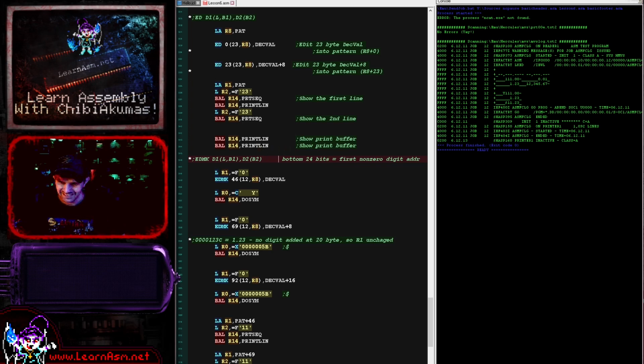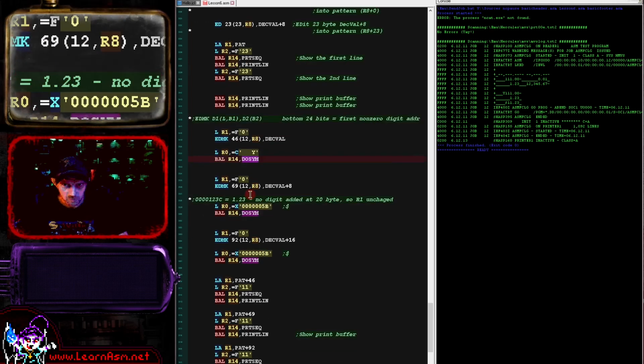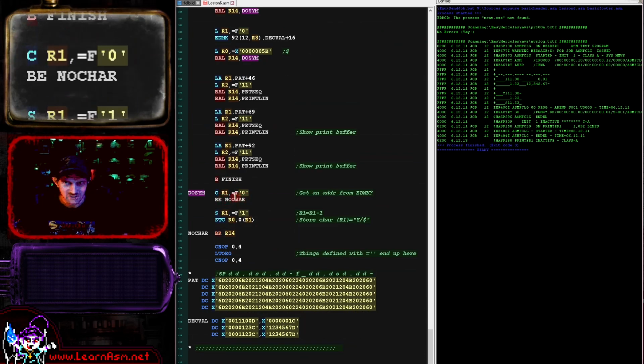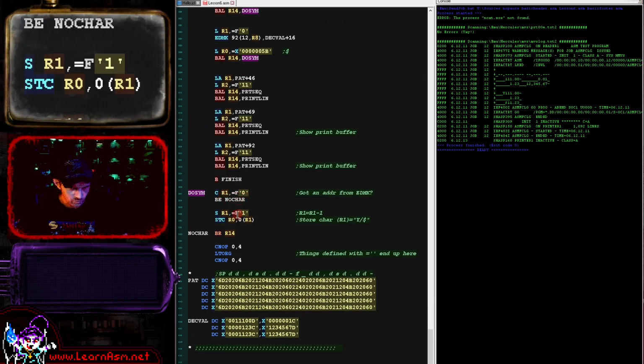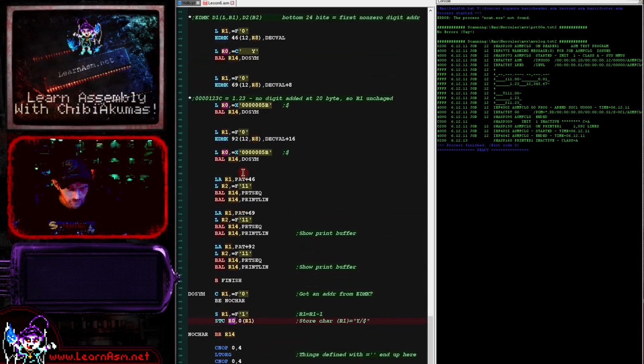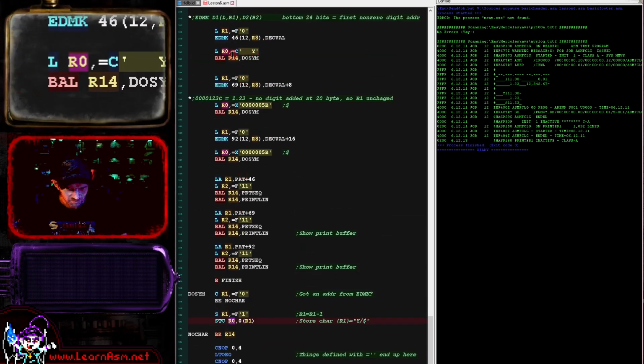So we had that significant start, which is where we show values whether there's anything to show or not, and that won't set that register value. It's only set if there was a value to set. In the case here, what I've done is I've exploited this, and I'm using this doSim command. Here we're checking if we actually found a character, but otherwise what we're doing is storing R0, and I'm loading R0 with some mock characters.